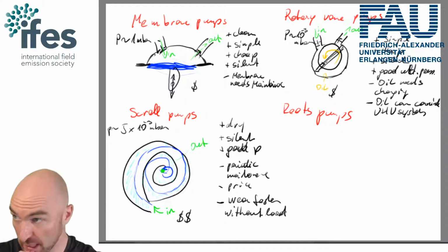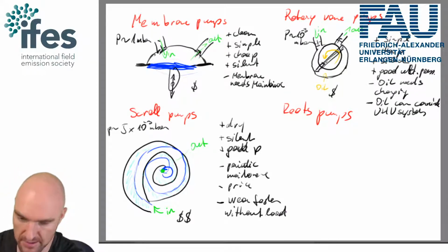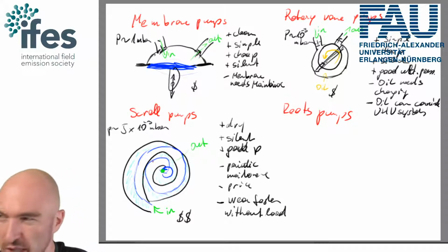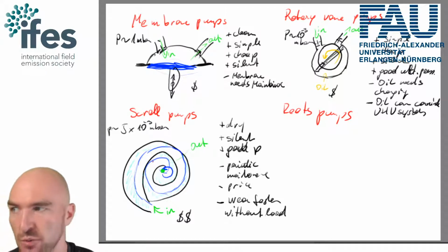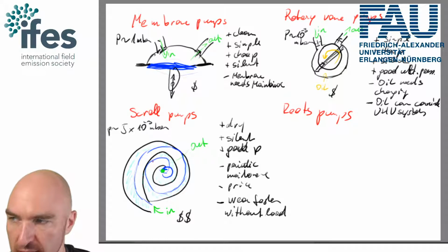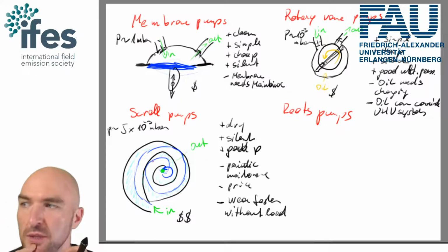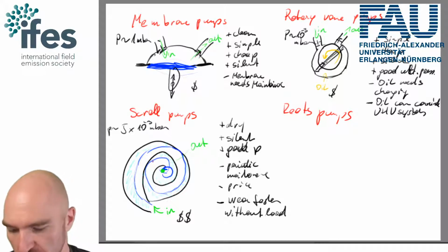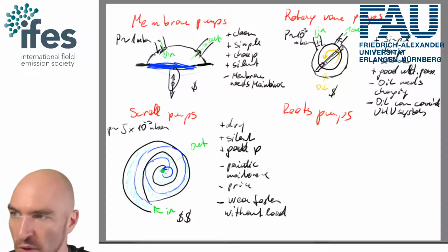faster without load. The problem in this case is that you have some friction between the PTFE and the scroll. The scroll is usually aluminum or steel, and so you will get some wear. And if you always pump very little vacuum, for example, backing an ultra high vacuum chamber, then the dust that comes from that friction will just stay in your pump, and it will increase the wear even more. As a result, they do wear relatively fast if you don't have a lot of load.